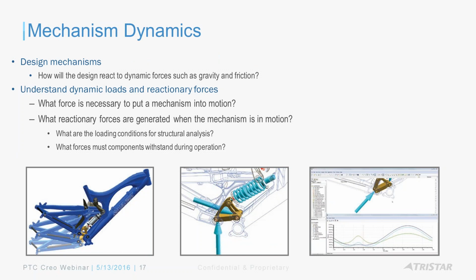And then mechanism dynamics. So this is the second tool that I was talking about, which is typically called MDO. There is a mechanism that's already built in to the Creo Parametric that you currently own. If you have an assembly, you're already able to use connections, right, when you apply constraints, and that allows you to create kinematic assemblies wherein all you're worried about is just the motion, right? You don't care about forces, you don't care about gravity, you don't care about external loads or reaction forces. That's the kinematic side. What is also called MDX, or mechanism dynamics extension.